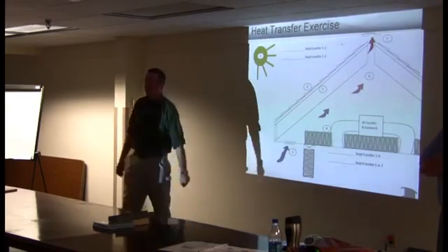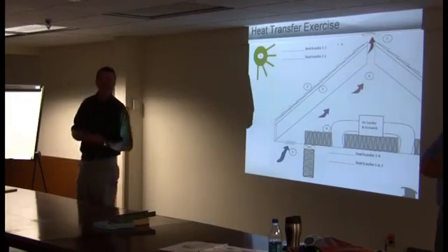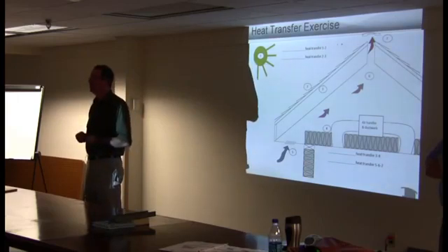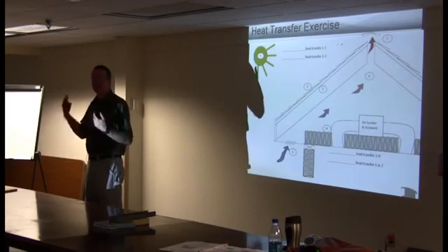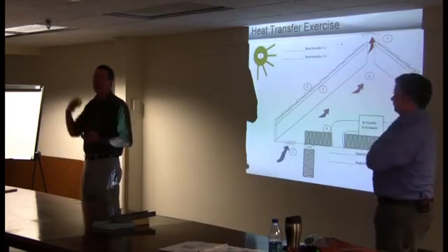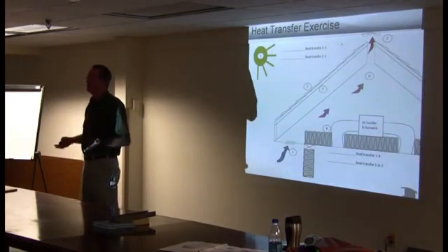And I think, through my course, and you've done a lot of energy assessments on existing buildings, I have seen many problems in commercial buildings where people don't understand what they're venting or why they're venting, and all they end up doing is letting in moisture and essentially bypassing their insulation. And it does not save energy at all.